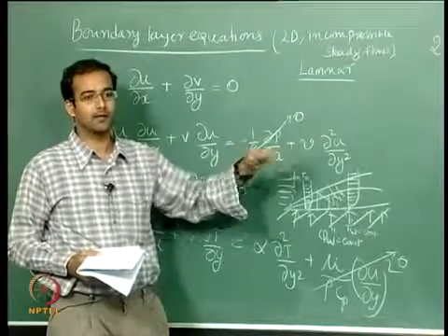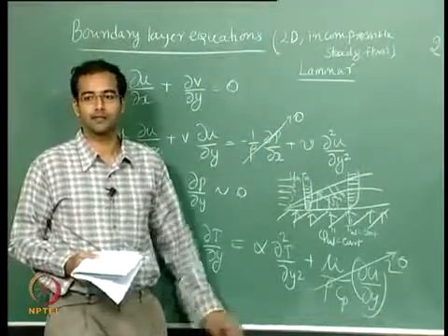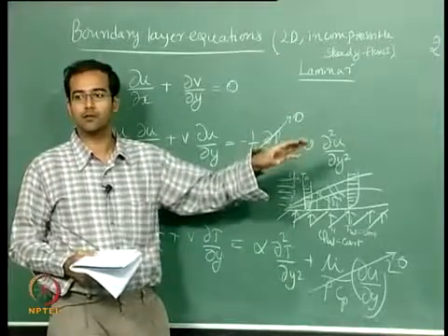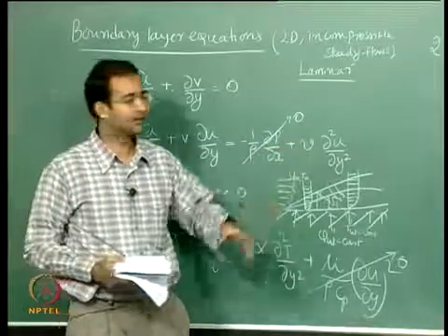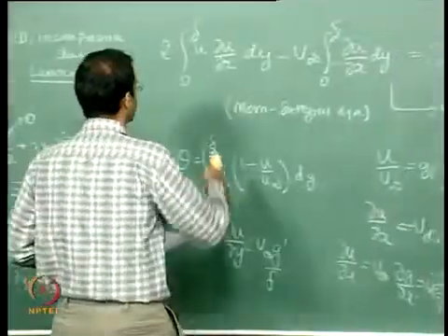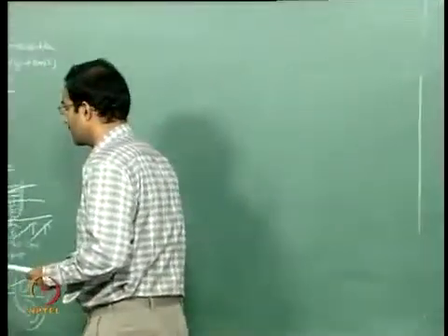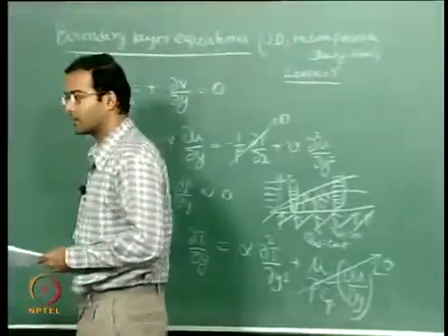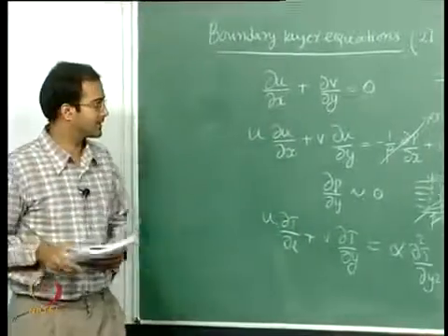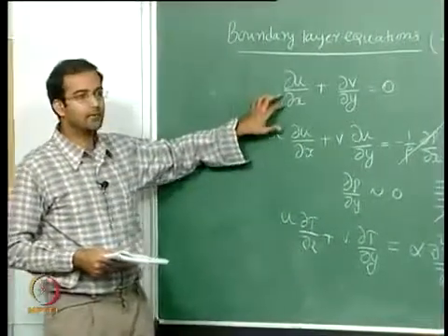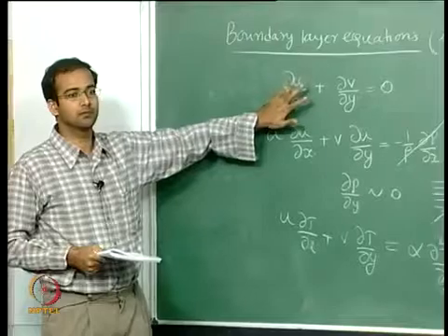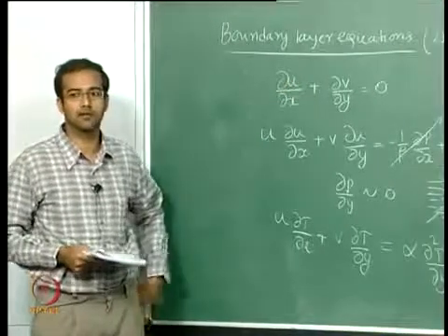That is the proof that you have a similarity solution, otherwise the similarity variable that you guessed is wrong. Correct? Okay, so let us go and check that. Now I have to introduce a function such that I can make the continuity equation redundant. I do not want to solve this. So what kind of function should I introduce?